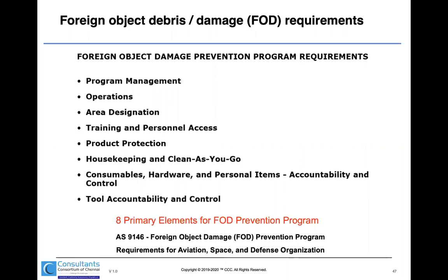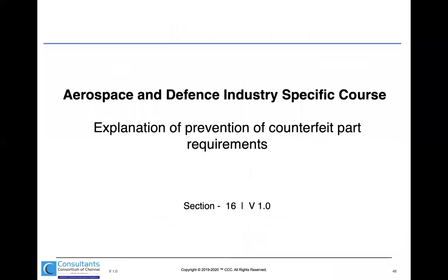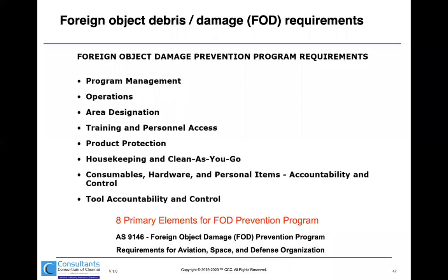See how many components I received from stores, how much consumed in operation, 10, 20, 30, right? Even during assembly and all, kitting, how many I have kitted from stores, how much consumed, what happened to the damaged part, excess quantity, shortage, everything we have to consider. Tool accountability also. These are some of the best practices used in the prevention of FOD. Okay, so this is with respect to FOD. Any specific questions with respect to FOD?